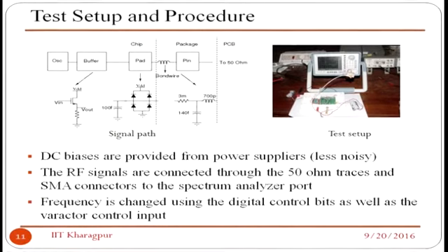So starting from inside the chip, this is how you have to route all your design up to the PCB. First is the buffer to isolate the effect of the loading, and then you have to use those bond wires. So a proper model should be ensured, then the pin, and finally it goes to the PCB, and then the PCB layout should be made so that the gradual impedance transformation occurs like that. Okay?